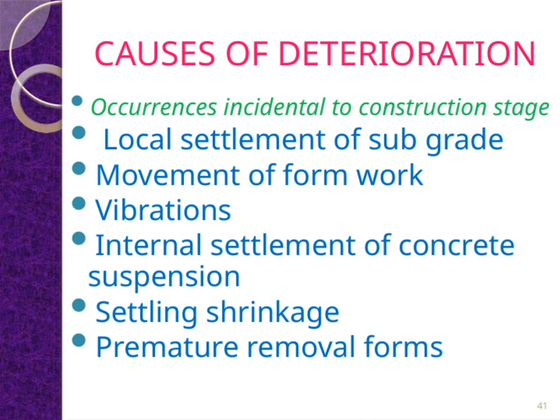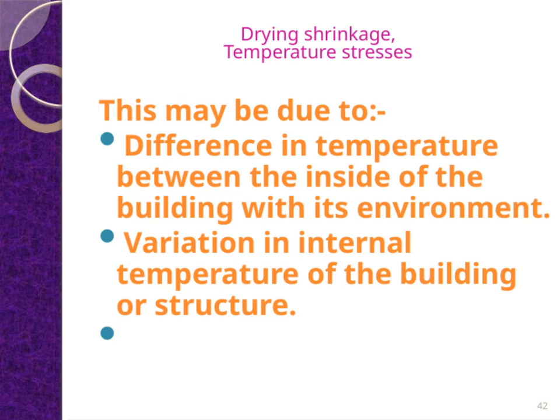Settling shrinkage is also a concern. As concrete loses moisture, it contracts, which can cause cracking if not properly controlled. Lastly, premature removal of forms is a critical issue. Removing forms too early before the concrete has gained sufficient strength can lead to deformation or surface damage. All these factors are causes of deterioration that need careful attention during construction to ensure the longevity and durability of the structure. This slide highlights some common reasons behind certain structural issues or material behaviors in buildings.